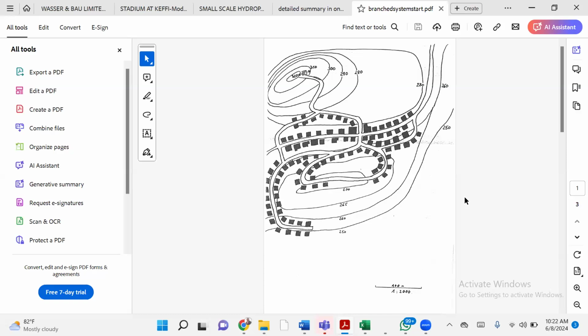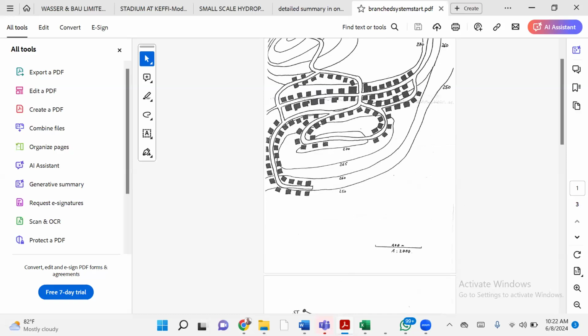That is why the first person that goes to site in the water reticulation design is the surveyor. The surveyor goes and takes the spot height. Why do we need the spot height? Why do you make sure you have the levels? Because 99% of water reticulation systems are via gravity. Because of energy, because of cost.